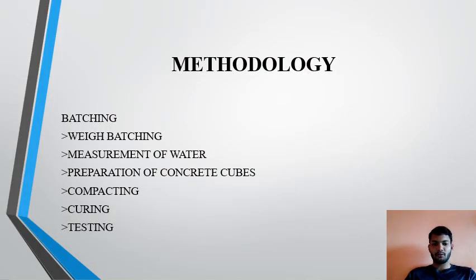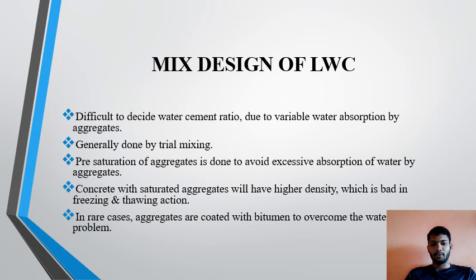Then methodology: batching, wet batching, management of the water, preparation of the concrete cubes, compacting, curing, and testing. Then mix design of the lightweight concrete: difficult to decide the water cement ratio due to variable water absorption by the aggregates. Generally, it is done by trial mixing. Pre-saturation of aggregate is done to avoid excess absorption of water by the aggregate. Concrete with saturated aggregate will have higher density, which is bad for freezing and thawing action. In rare cases, aggregates are coated with bitumen to overcome the water problems.